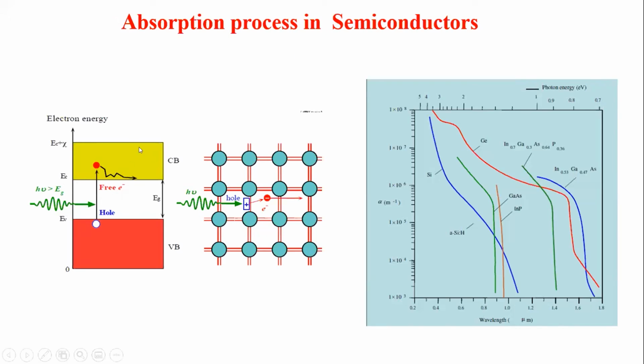So normally, when you have a semiconductor, I told you it can be excited in different ways: thermal excitation, optical excitation. Let us concentrate here on optical excitation. When shining a light on your semiconductor, whenever the energy of the light is greater than the band gap of the semiconductor, the light will be absorbed. The energy is absorbed, so it has to do some work. Due to this absorption, the bond will be broken, and the electron will be freed in the lattice.